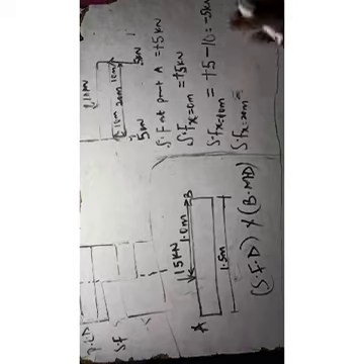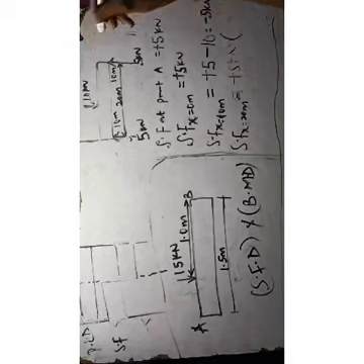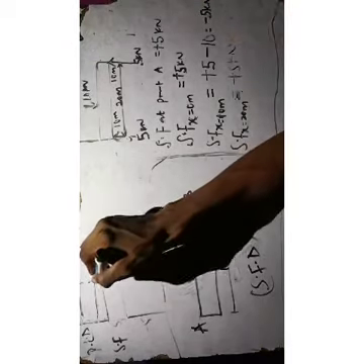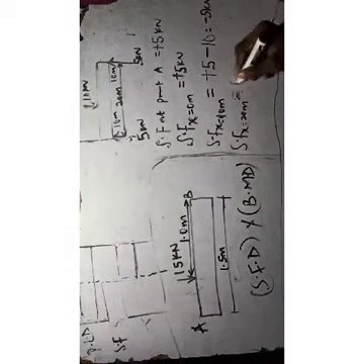Or you can simply say plus 5 kilonewton. The plus 5 kilonewton must be accounted for at the edge, okay? Now if it's plus 5 kilonewton, when it gets here, this is 0, right? This is minus 5. Minus 5 plus 5 will give you 0. But if you don't get that, simply do this calculation and you have your 0 kilonewton.